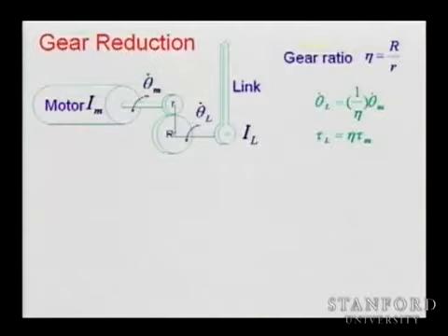So you take a motor. If the gear ratio is 1, basically you have direct drive and you need a big motor to produce a torque, right? But this big motor is heavy, and with the robot, putting a heavy motor here is a problem. So what do we do? We put higher and higher gear ratio, reducing the size of the motor. And we can achieve the torque because we are using a high gear ratio.